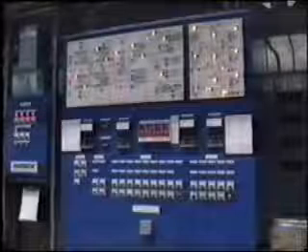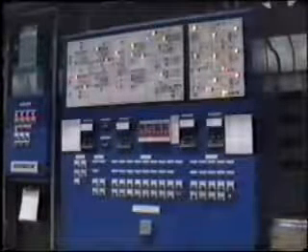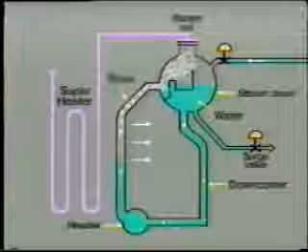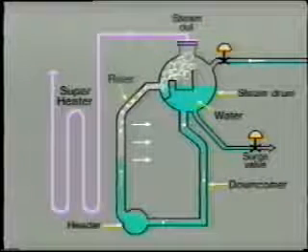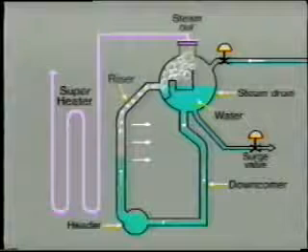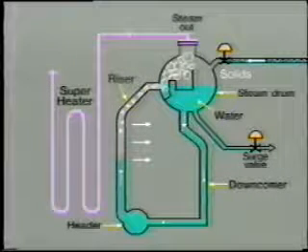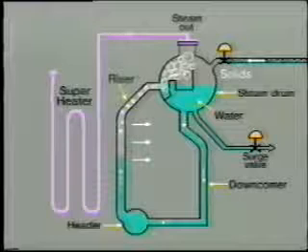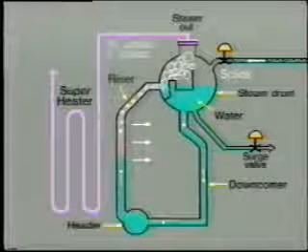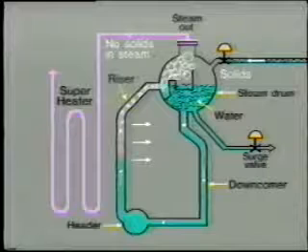Control of the boiler water condition is extremely important, and one of the major factors is conductivity. Conductivity is actually a way of measuring the solids content in the water. Even though we go to great pains to keep the boiler feed water as pure as possible, it is inevitable that some small quantity of dissolved solids enters with the boiler feed water. Now, when this water is evaporated into steam, the solids remain in the boiler water and eventually accumulate to quite